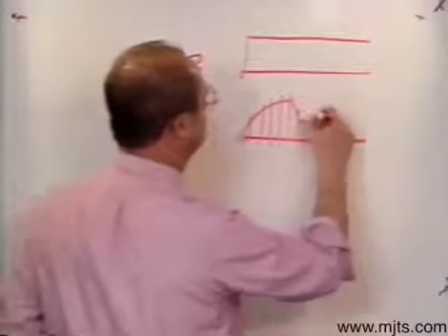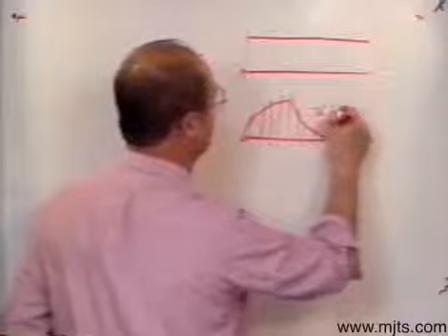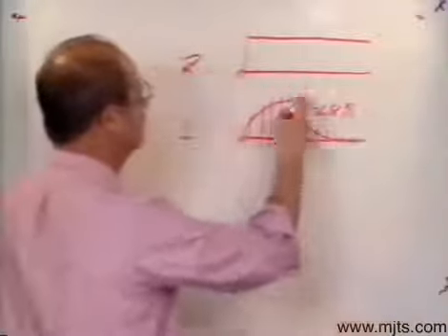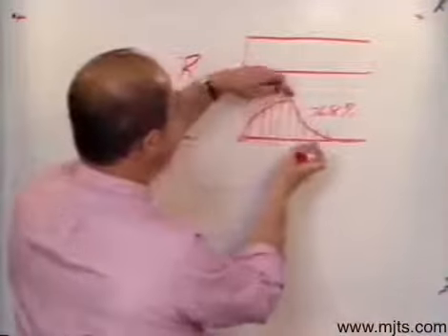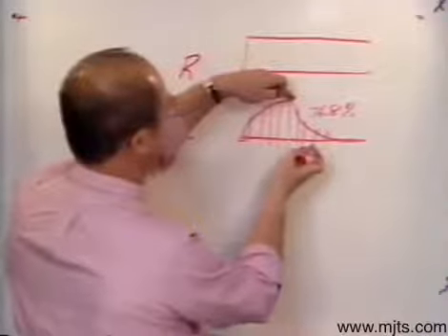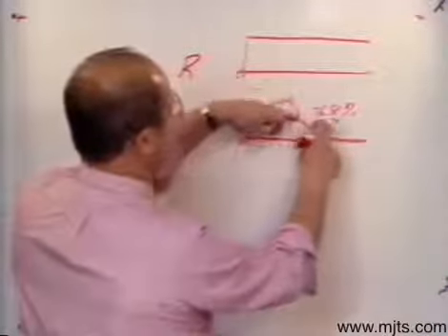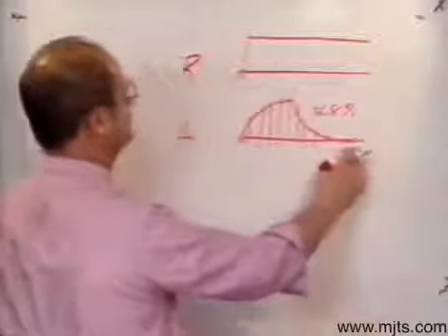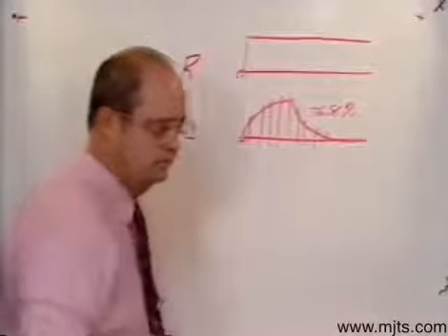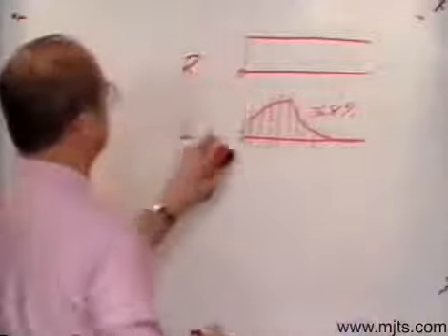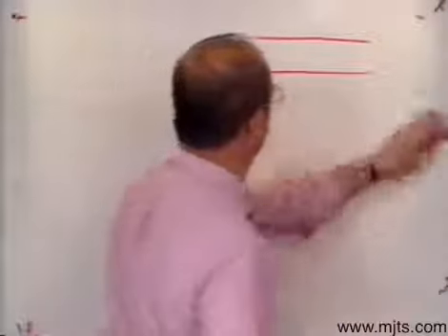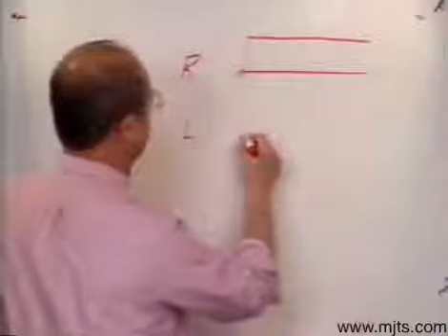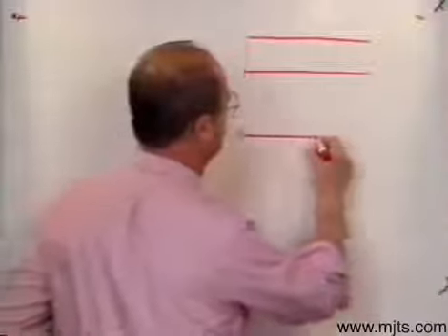What it does is go to 36.8% of the difference between full value and 0. The next time constant will be 36.8% of that, until it goes through 5 time constants to get back to 0 again.